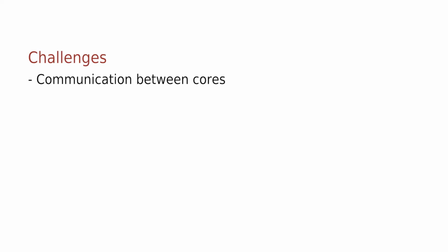What are the challenges then? Well, the two worlds need to communicate, so some kind of inter-processor communication must be implemented. I will not go into detail about this. That is a topic for another video or even webinar. But there is a framework in place and it's working well. It's called RPMSG. You also need to plan for debugging and get a good task partitioning and separation in the system. None of these issues are unique to HMP. They are common for any system partitioned into multiple execution units. But they get more noticeable if not handled correctly in an HMP system.